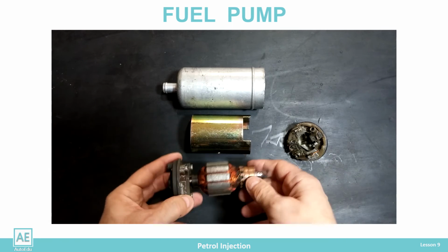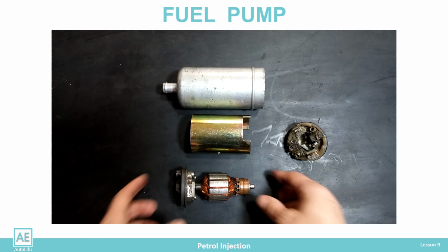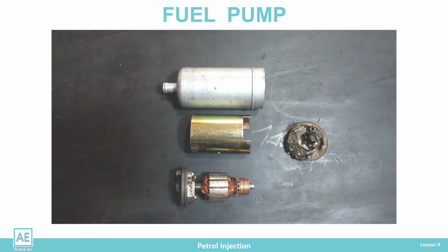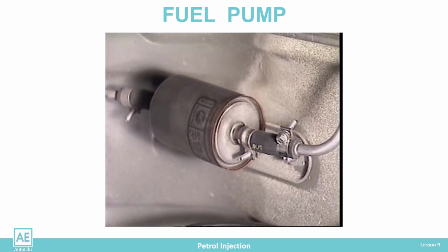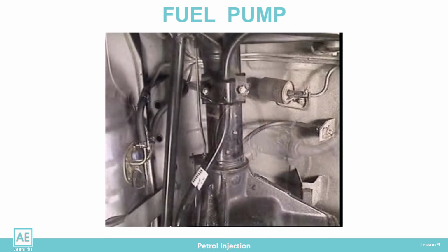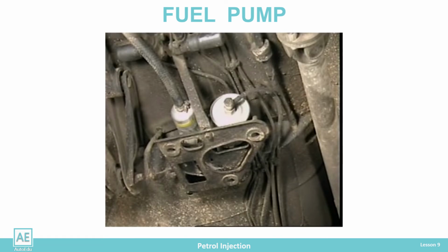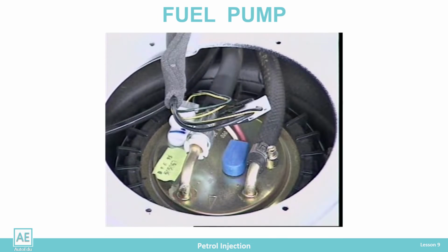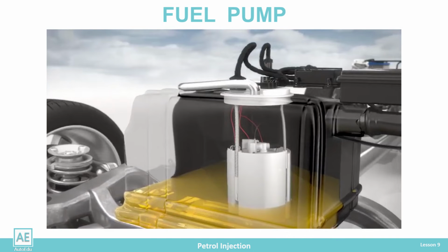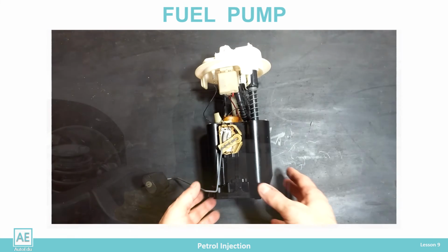The fuel pump can be outside or inside the tank, submerged. With older injection systems, the pump was outside the tank and often under the vehicle. Due to poor exploitation conditions, the housing rusts and it can leak. Also, electrical plugs get dirty and corrode faster. When the pump leaks, it must be replaced with a new one.